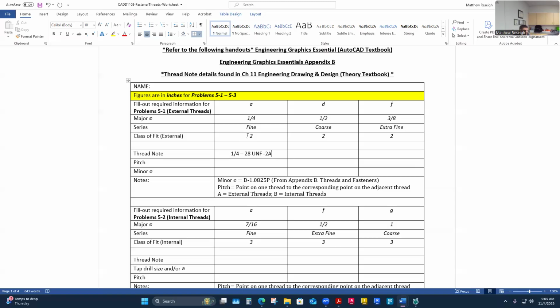And so it prevents maybe the wrong fastener from going on in the wrong application, getting things in the wrong place. So sometimes designers and engineers will use it strategically so that parts can't be incorporated wrong. And it's used for other reasons too, but generally right hand threads are more common. So we just drop that and we leave ours blank.